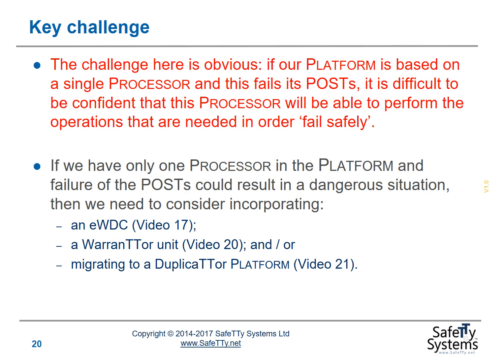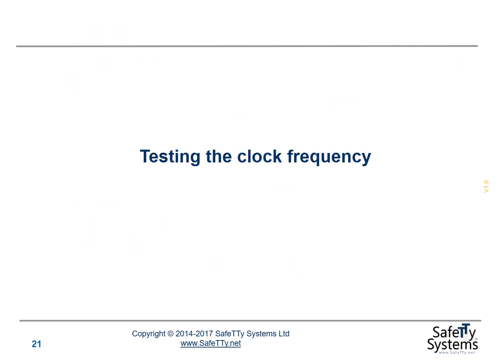The key thing here is, unless you can be confident that you will be able to enter an appropriate safe state in the event that you fail your POSTs, you need to consider whether simply basing your system on a single processor is an appropriate thing to do. So let's begin by considering how we can test the clock frequency.